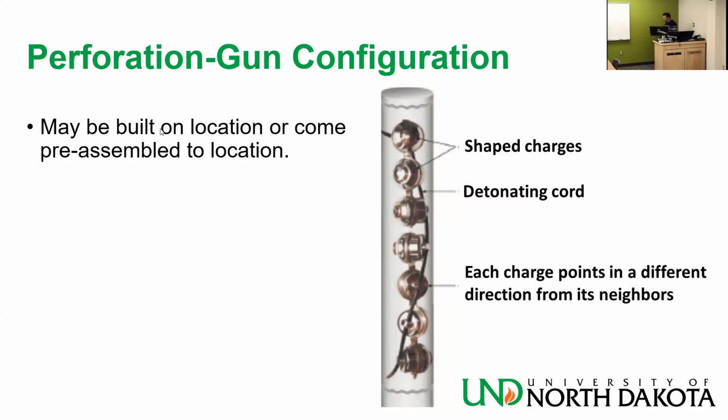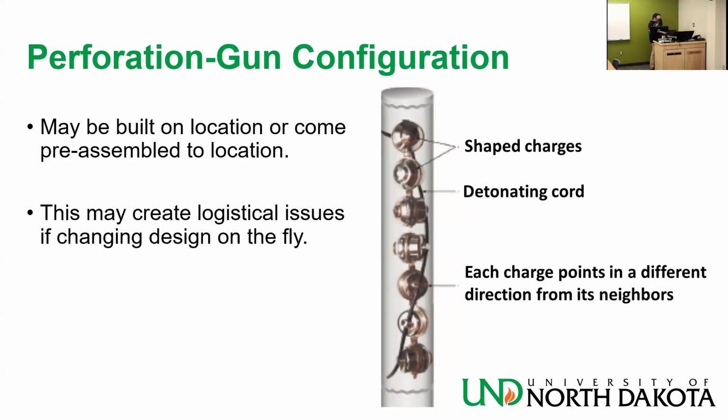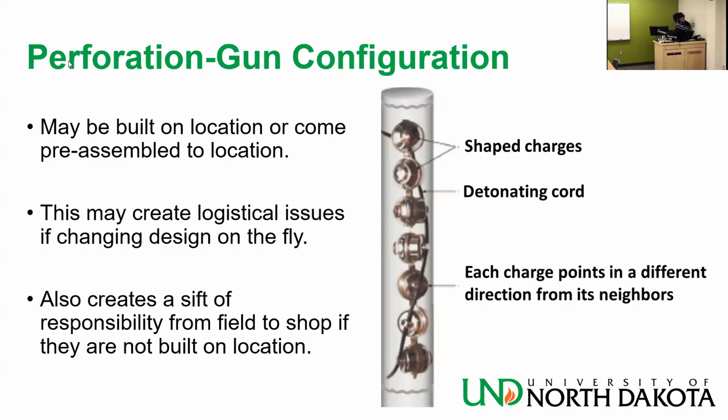Many times, the perforating gun is built on location. This may create logistical issues if changing the design on the fly. You need to have enough to build the design that you like. Otherwise, again, you have to get the expert, go back to the company's headquarters and bring more stuff. You don't want that. Building on location also avoids a shift of responsibility from field to shop, which happens if they are not built on location.